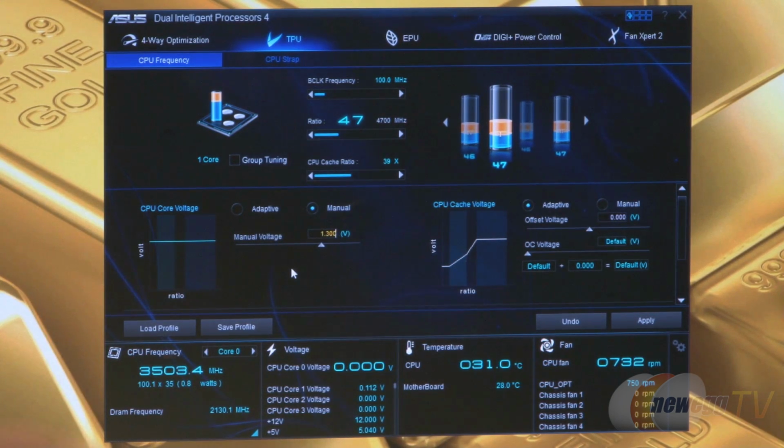your value assessment. And you can also see that we've color-coded this as well, so that we can help provide you insight into what voltage levels you might be at. So if I want to jump to like 1.450, you can keep in mind that that's an unsafe voltage to be at. It's a bit high for this processor. Versus if I go back to the 1.275, you can still see that you're in normal territory in terms of your CPU voltage.